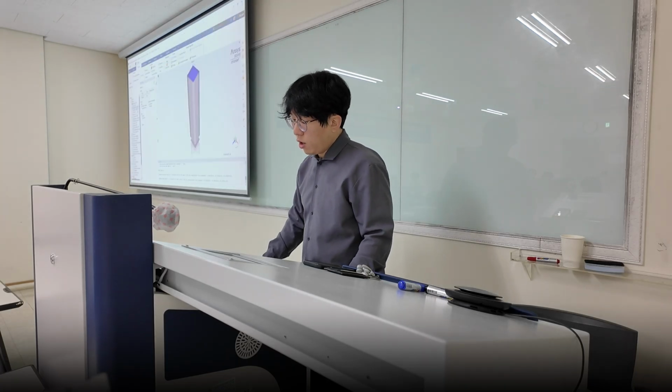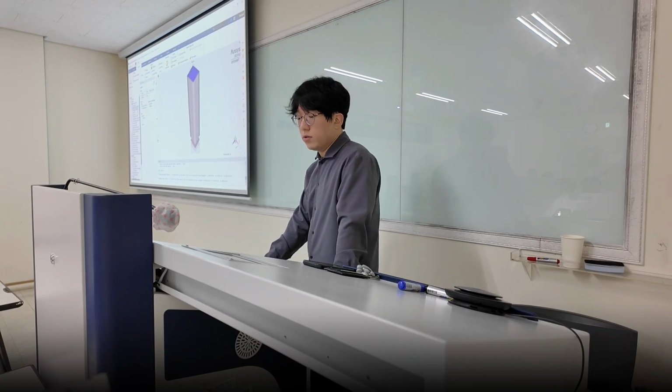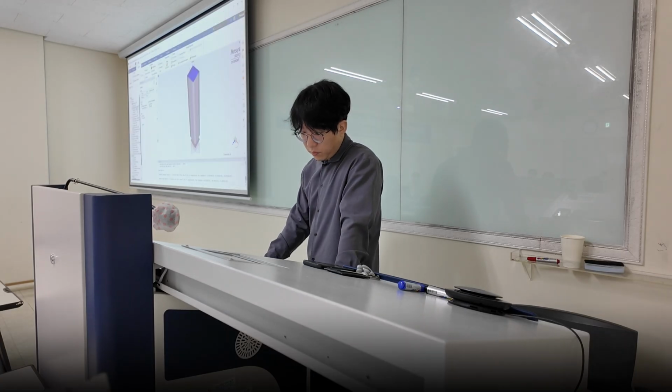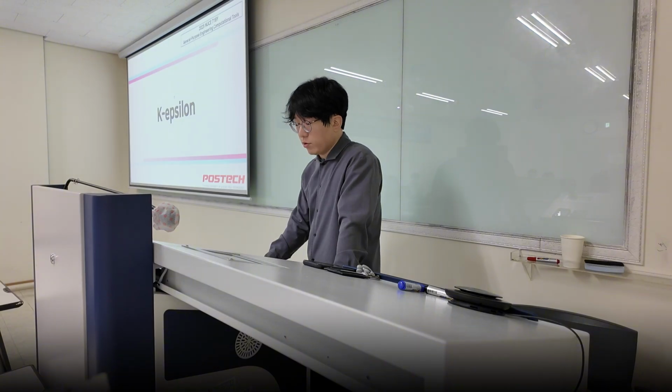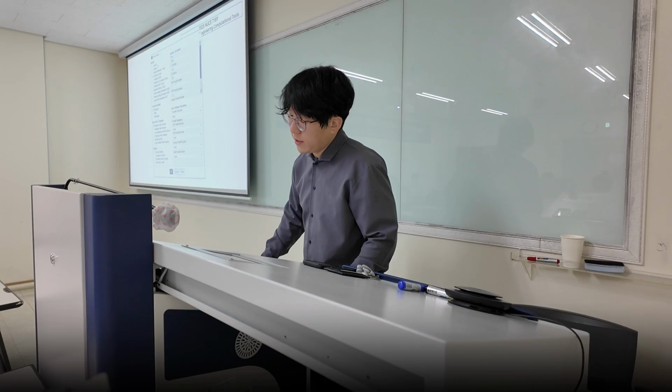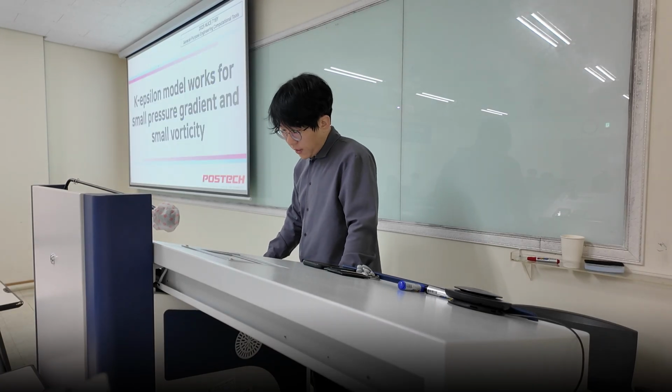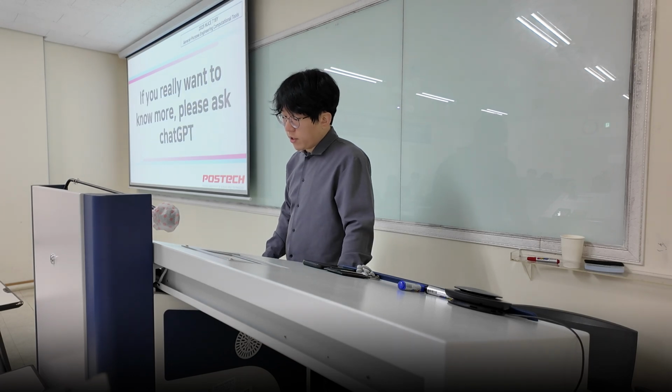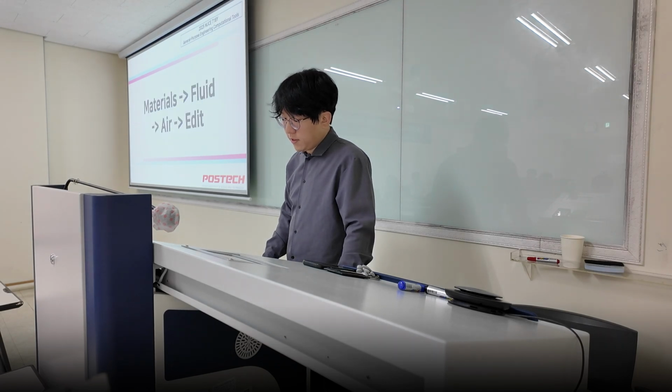Then we're going to first define the model. I just randomly chose k-epsilon, but you can choose other models. You can pretty much choose laminar as well, depending on the Reynolds number range. And you can search this online yourself.